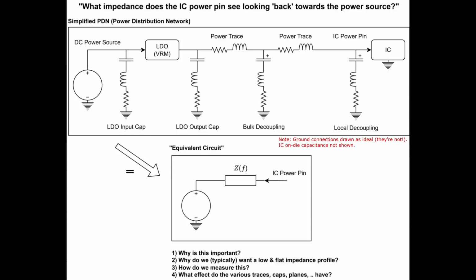And FPGAs or some other more advanced integrated circuits will have even more stringent voltage rail requirements and might have very high current requirements in short periods of time. So how do you ensure that your power, which has to go through all of these components, all of these non-idealities such as series resistances and inductances, still keeps those margins, those voltage levels, and can sink and source that required amount of current in that typically short amount of time? How do you ensure that? And how do you measure that that system would even work? And that's where we come into the whole topic of power distribution networks.